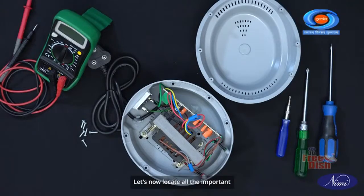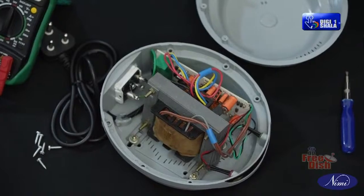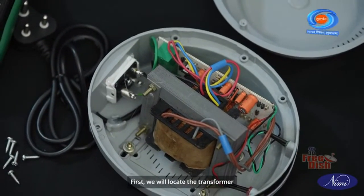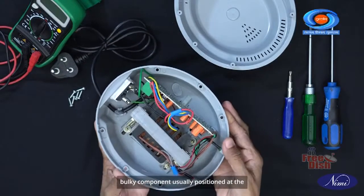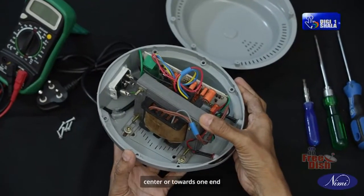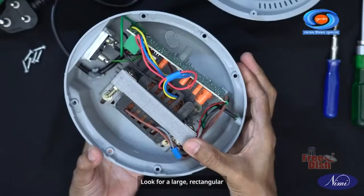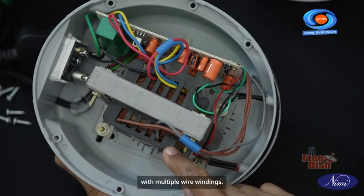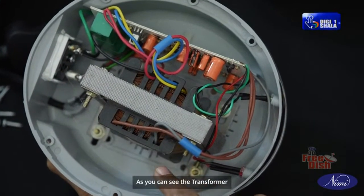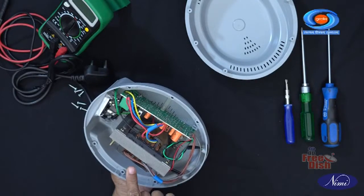Let's now locate all the important components of the voltage stabilizer. First, we will locate the transformer within the stabilizer. It is a prominent, bulky component usually positioned at the center or towards one end of the stabilizer. Look for a large, rectangular or cylindrical structure with multiple wire windings. As you can see, the transformer has 2 windings, primary and secondary.